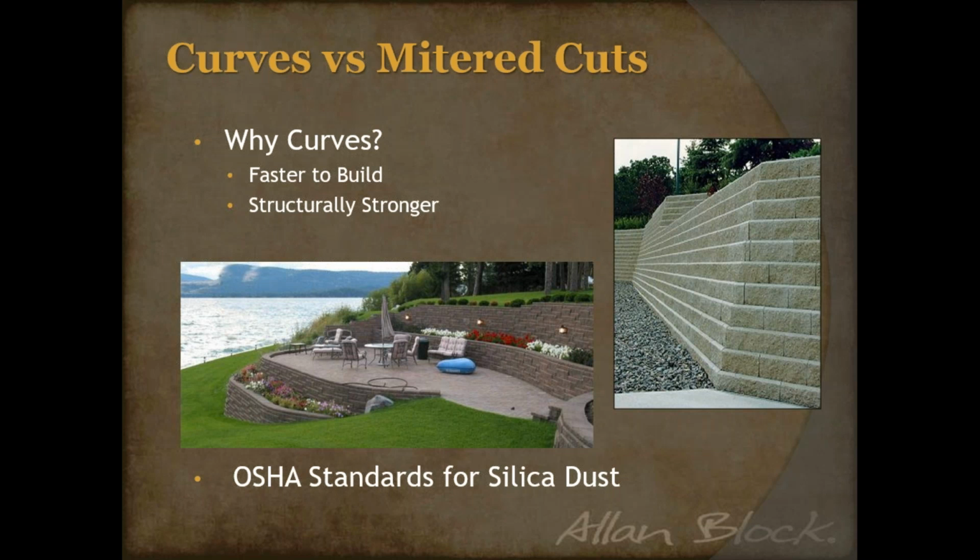So they are looking for everything to be wet sawed and to have a plan to handle the concrete dust. You can no longer just fire up the saw and make that cut and let the plume of silica dust filter over the neighborhood. And granted, we don't have a lot of OSHA inspectors driving around streets all the time, but that is the requirement. If you are generating dust, that is a violation.